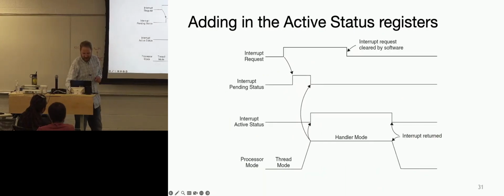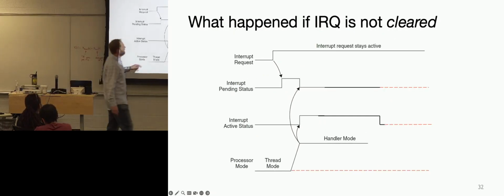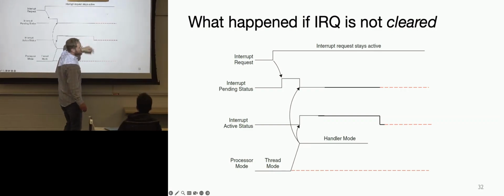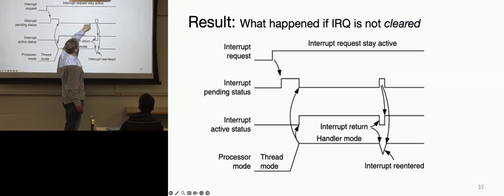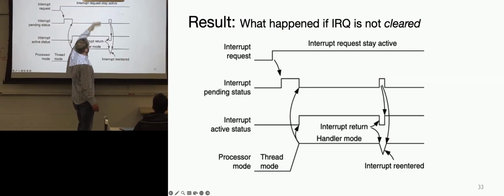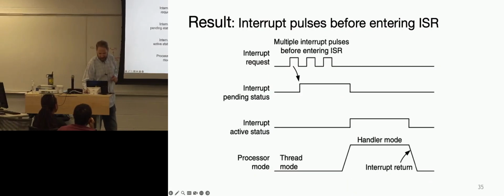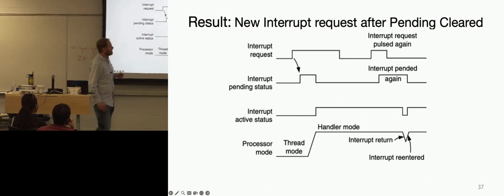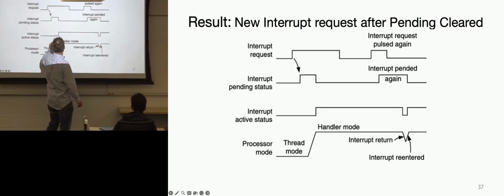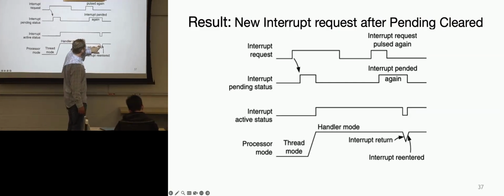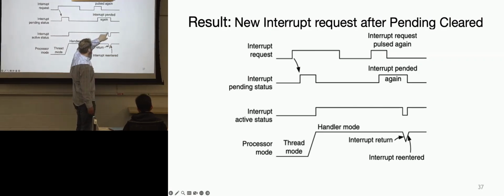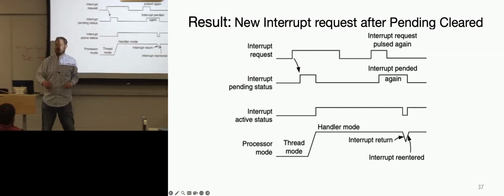Let's see, where's this example? In this example, you didn't have a positive edge trigger, so it waited. Come back here. Then you had to get out of active for pending to go high again. That's just a level set, but if it's a positive edge trigger, then you can actually assert pending again. The same thing happens on the end here, right? Oh, is this the right one? Yeah, this is the right one. Here, this ended, and then you had to go right back; you were out of active for a moment and back in. It's just that pending somehow got set. How did pending get set? Because of the positive edge trigger. This rarely comes up. Yes?